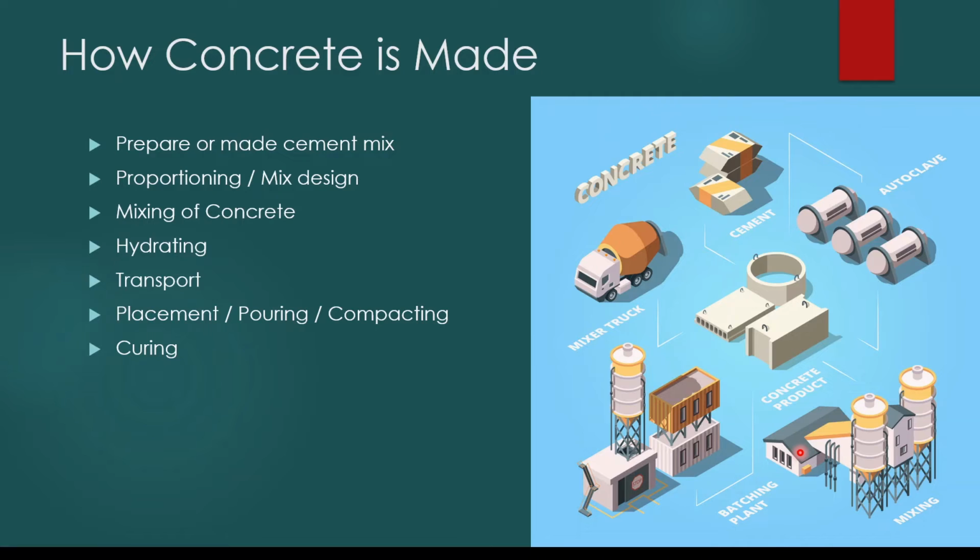Otherwise there will be issues, because once you pour the concrete, you can't check the strength until after 7 or 28 days. Before pouring, you should know this concrete has adequate strength. So that's why we do the mix design. We do the mix design trial mixes, then we check the strength, and if it is okay we proceed. So that's also something we have to keep in mind. That's all about the mix proportioning and mix design.